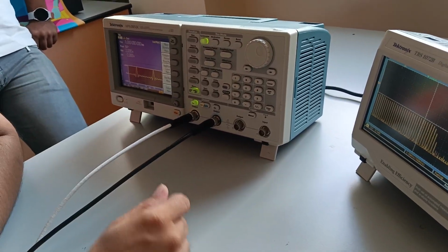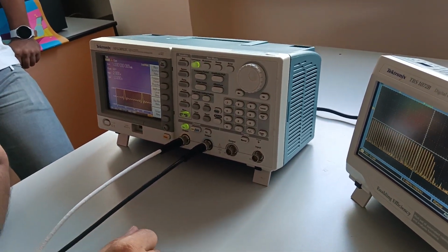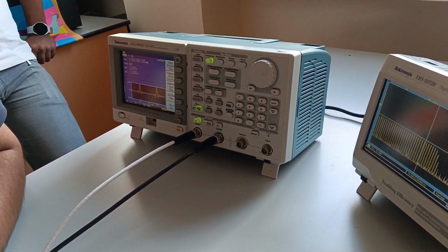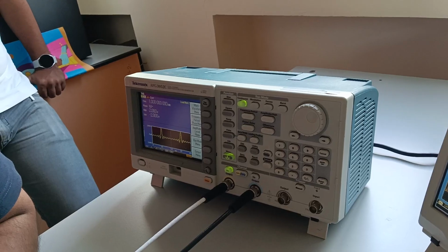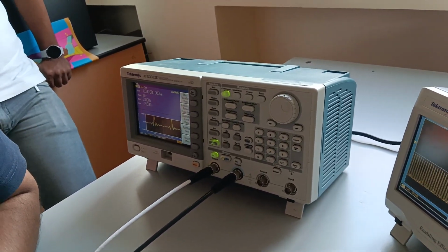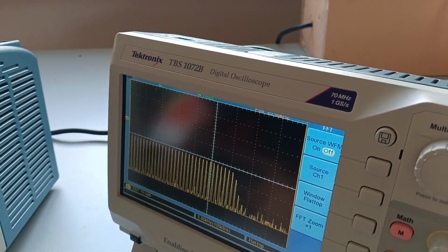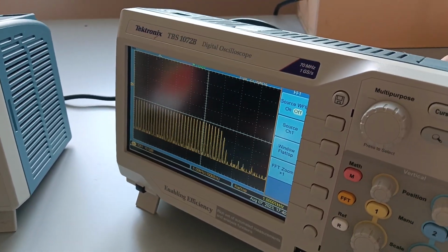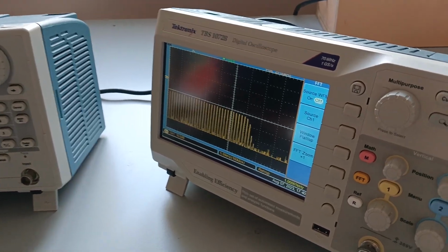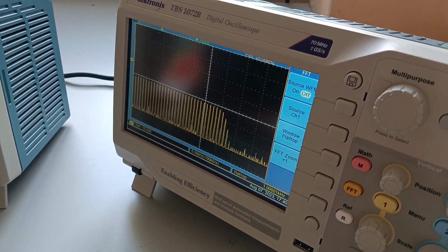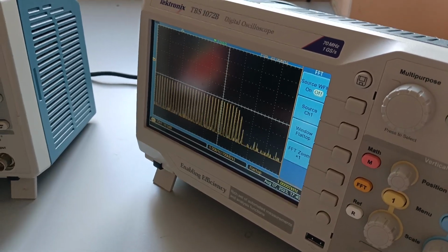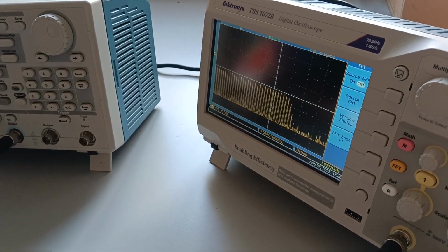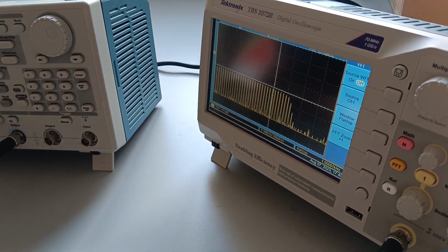See, we have something like, you know what function is this? Fourier transform. No. What is this function? It's a sinc function, sin x by x. Look at its Fourier transform. But what is the Fourier transform of sin x by x? Step function. This is not a step function. It is not a step function because for Fourier transform you have to integrate from minus infinity to infinity. Here you don't have that. You have only finite sampling.